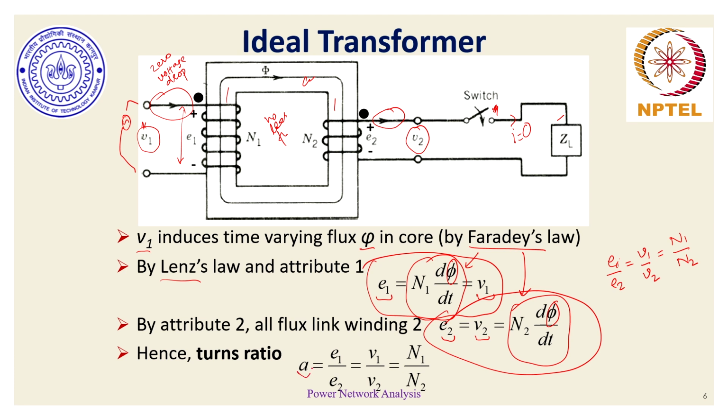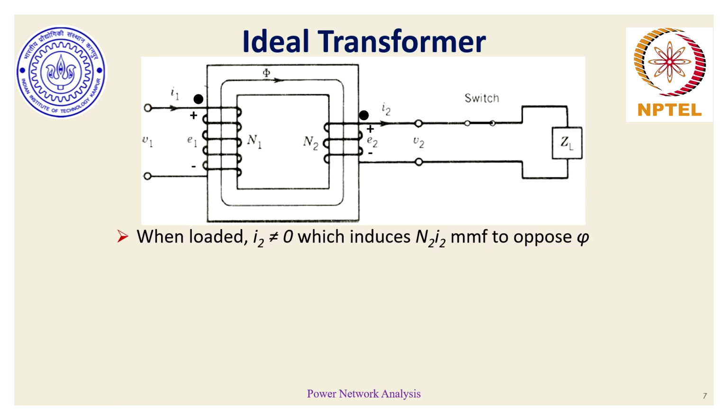We often associate small a with it, that's the notation which I follow, others can have different notation. The turn ratio of a transformer is nothing but the ratio of primary voltage divided by the secondary voltage. If I know my primary voltage and the number of physical turns on the transformer, I can also find the corresponding secondary voltage which would appear at the load.